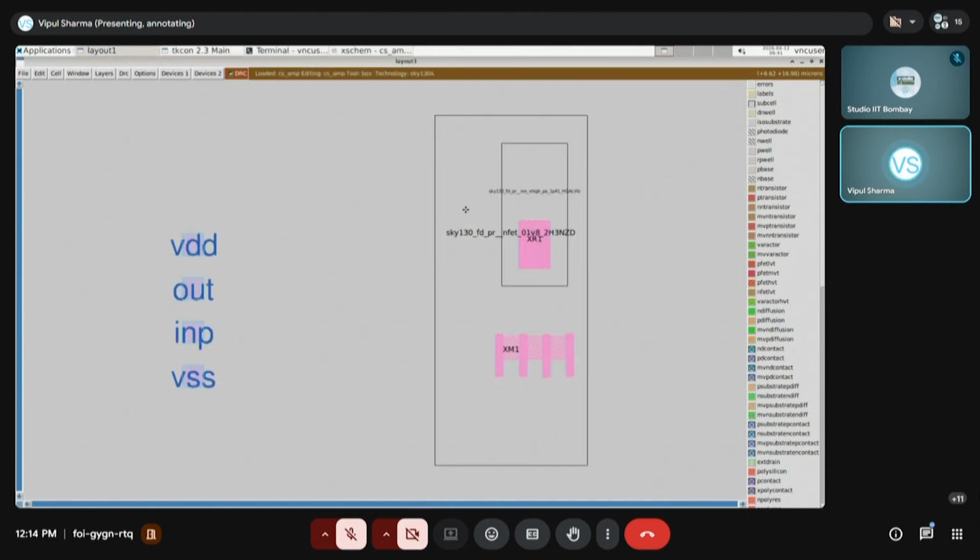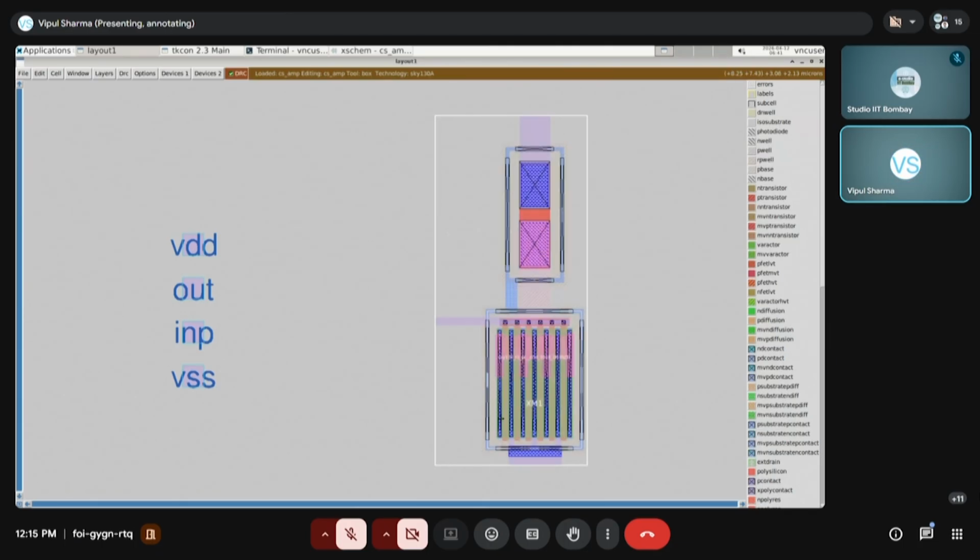When you open it the first time, it will open like this. You will not be seeing the inner layers of this layout. So press the X key on your keyboard, and everything becomes visible again. Okay, so this command was not running. I will select my pin and move it here. Yeah, so this is how it moved.